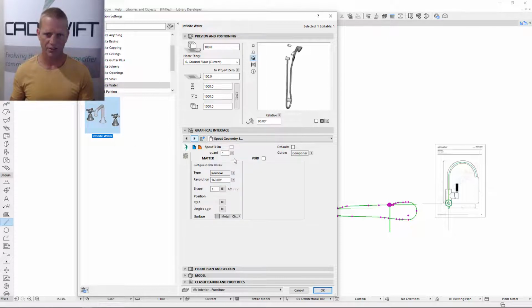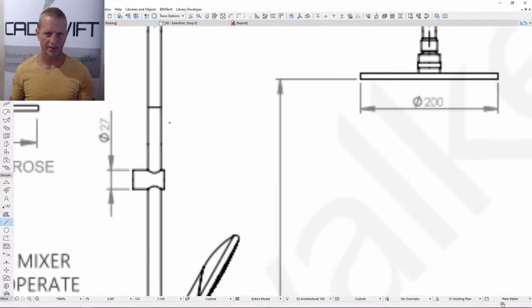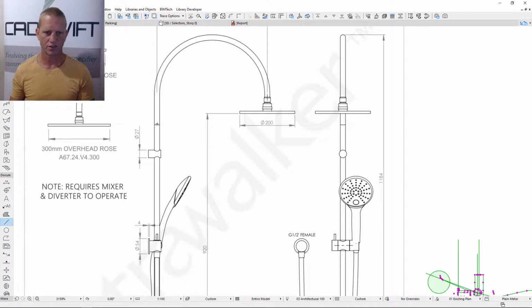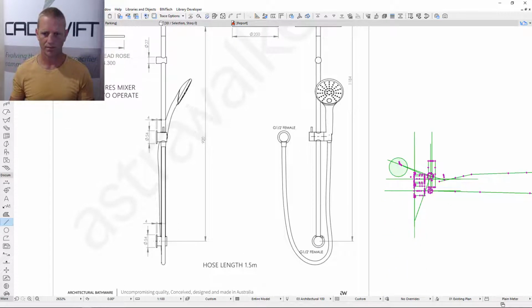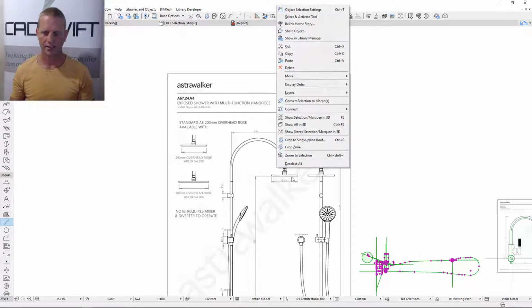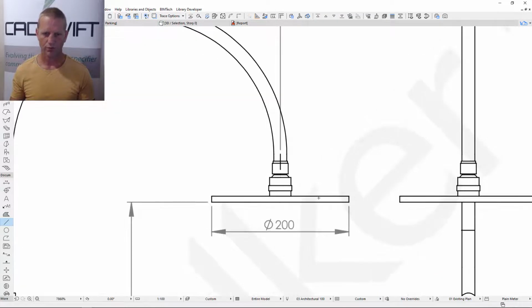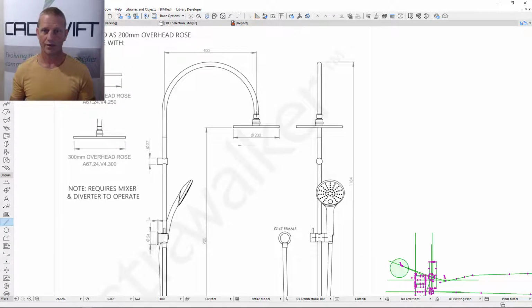So let's go to Spout Geometry 3. I'll just click OK here and have another look at the drawing. You can see it doesn't have any variation, so it's easy enough to do this as an extrude, in fact, we'll probably do it as a tube all the way around. We'll start here, do a tube that runs from this point down here, up and all the way around to the shower head, and then the shower head will be a revolve using the second piece. Now remember we have 2 pieces of geometry, which effectively gives us access to 4 pieces of geometry that we can use here.